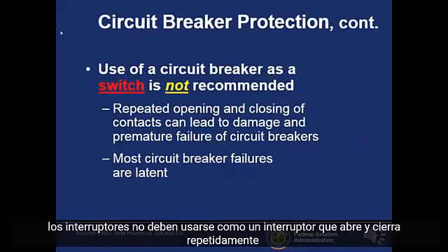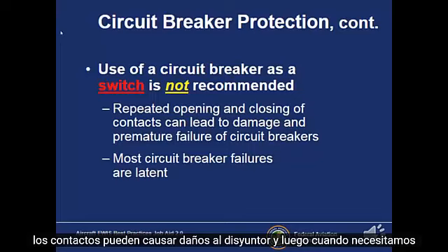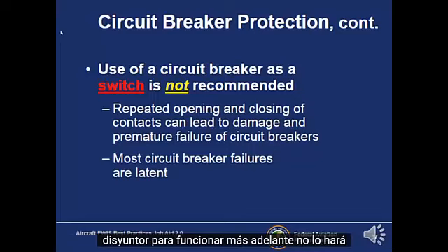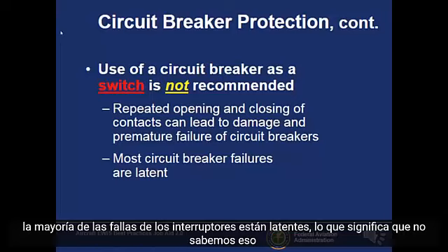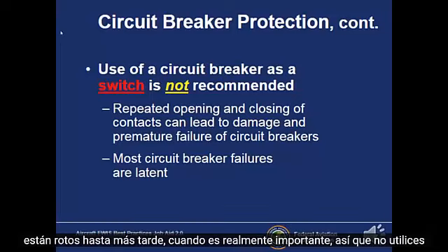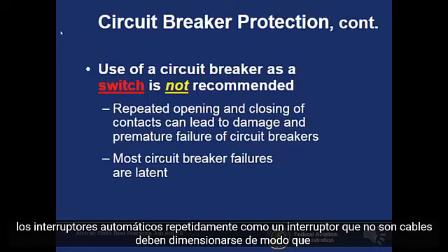Circuit breakers should not be used as a switch. Repeatedly opening and closing the contacts can cause damage to the circuit breaker, and then when we need the circuit breaker to function later on, it won't. Most circuit breaker failures are latent. That means that we don't know that they're broken until later, when it's really important. So please do not use circuit breakers repeatedly as a switch. They're not.